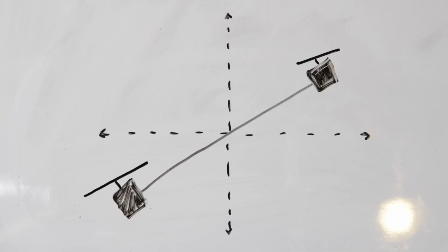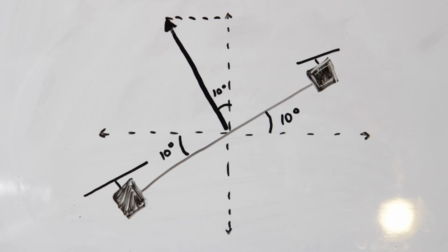Now that I have the numbers for just hovering, I can calculate the numbers for when it is at an angle, let's say 10 degrees. I can draw out a diagram and fill in all relevant angles by simply using complementary and supplementary angles. In this diagram, I separate the thrust vector into the horizontal thrust and vertical thrust.